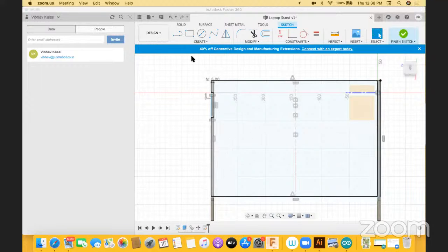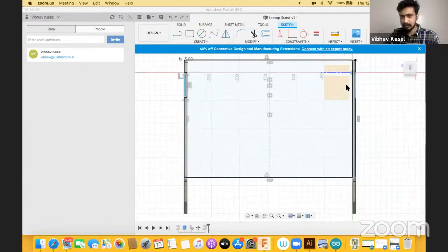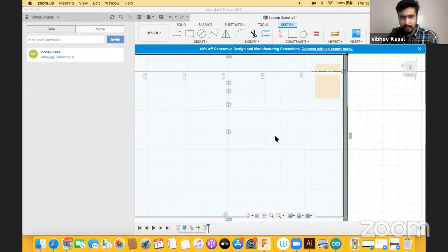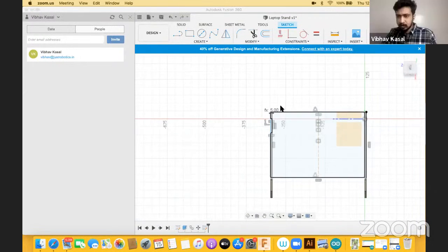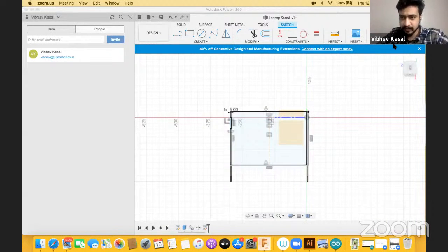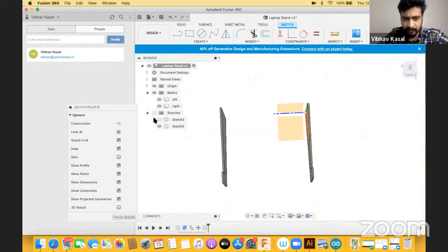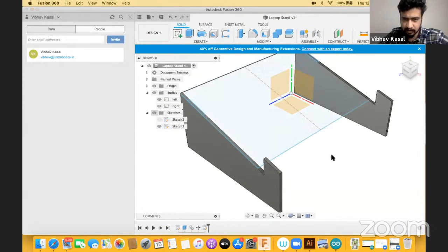It is better now. Yeah, so I just ended a few things and restarted the module. So let's see. So now I have these two things. I could extrude this, but instead I want the finger joints to appear, right? So what I've done is I will finish the sketch now. I'll finish the sketch. If you can't see the sketch, you have to turn this on.